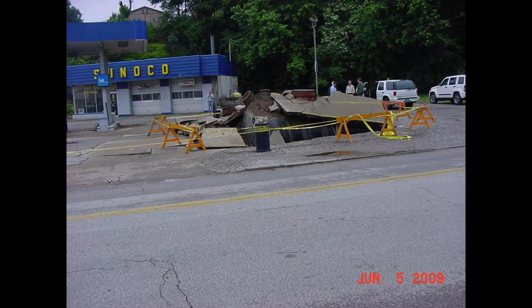So if the water table gets pretty high, let's say it's been wet weather, and the voids in the soil grains begin to fill up with water, now those hydrostatic forces are pushing upward on the tank. And in this case, the weight of the tank, the weight of the soil, and even the weight of the concrete acting downward, all of those forces were less than the buoyant force pushing up on the tank.